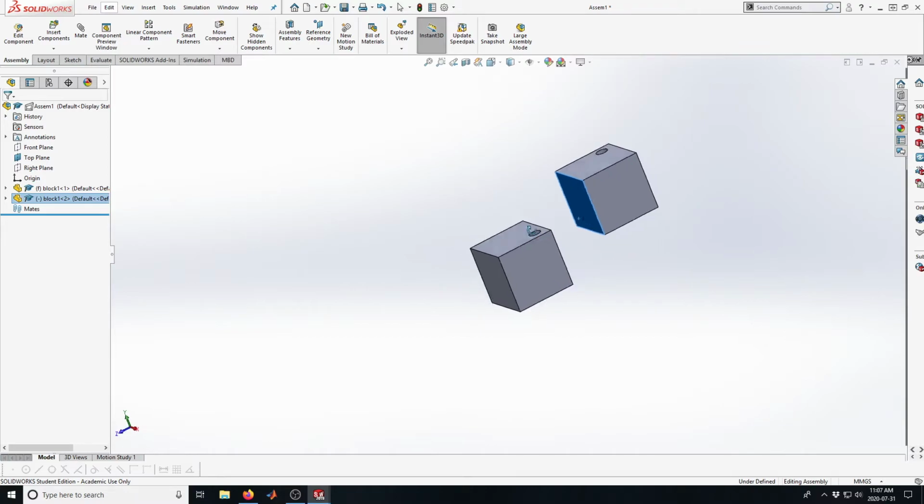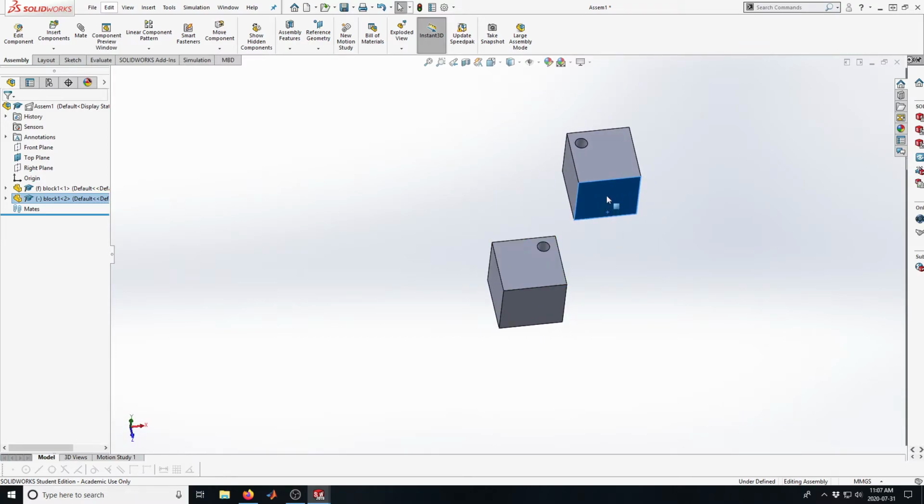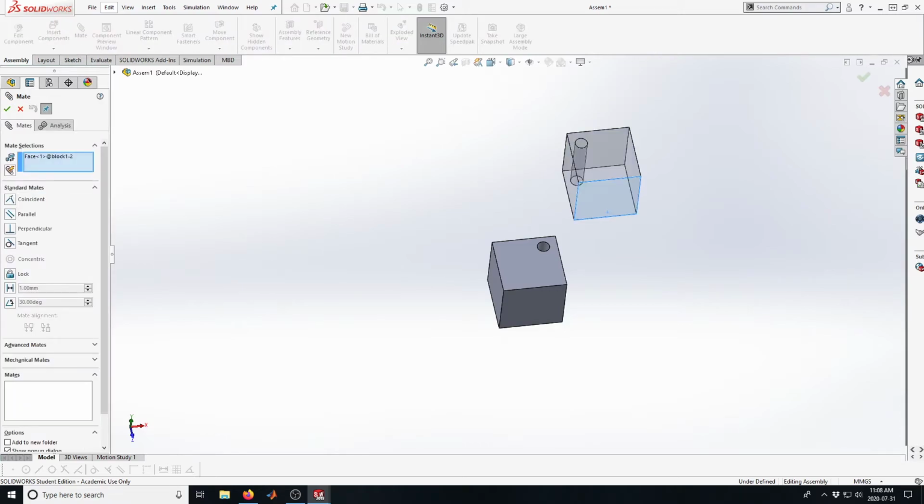And in fact, while it managed to get kind of close to this guy, it's really hard sometimes to tell that you placed something in the view plane but a mile away distant. That's hard to sometimes get out of. So you'll see that there's these mate tools, and if you click up here, there's a little paperclip sort of thing, and if you select that, then it's enabling you to create a mate. This is going to give this part some kind of relationship to the part you've placed already.